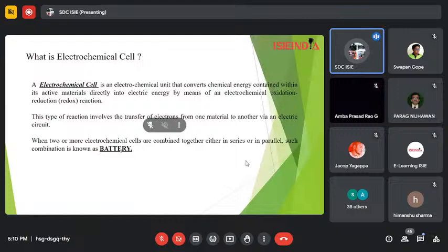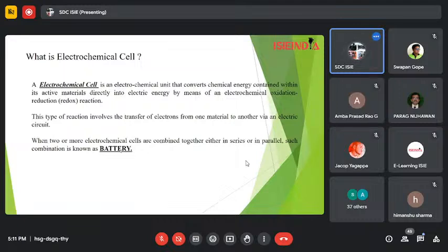For your information, when we connect positive terminal to negative, and again negative terminal to positive, positive terminal to negative, it is a series connection. And when we connect parallel to parallel, what does that mean? Positive to positive, positive to positive, and on the lower side, negative to negative, negative to negative. That will be a parallel combination. When we combine the cells in this manner, either in series or parallel, it forms a battery pack.